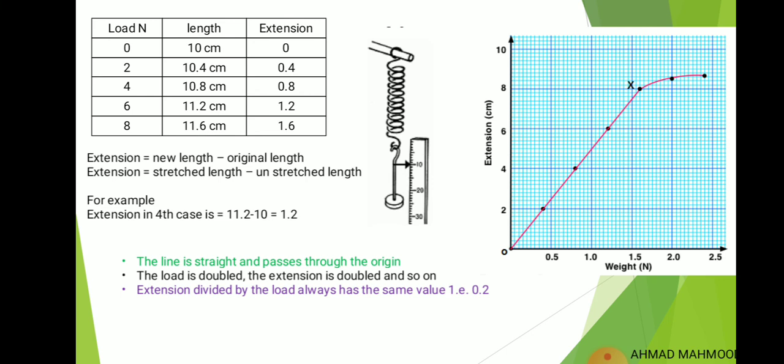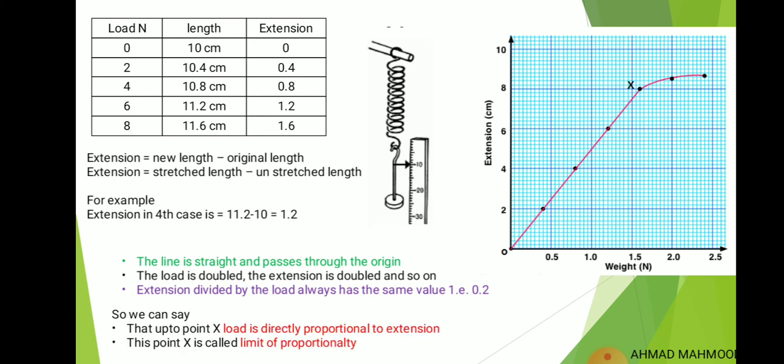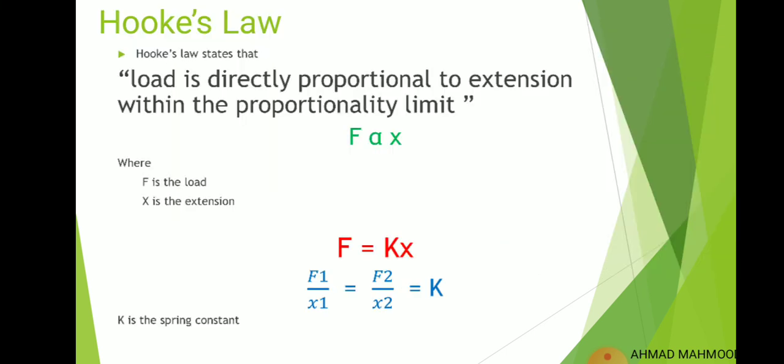These are the observations of this experiment. So we can say that up to point X, load is directly proportional to extension. And that point X is called the limit of proportionality. Extension is also called elongation or deformation.